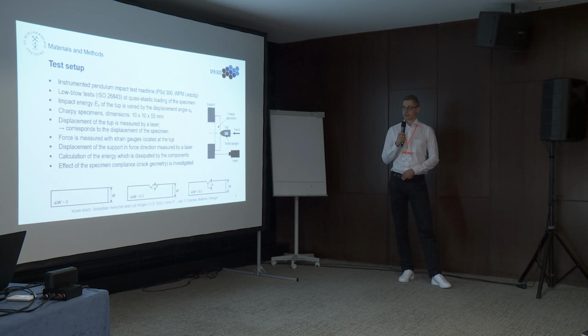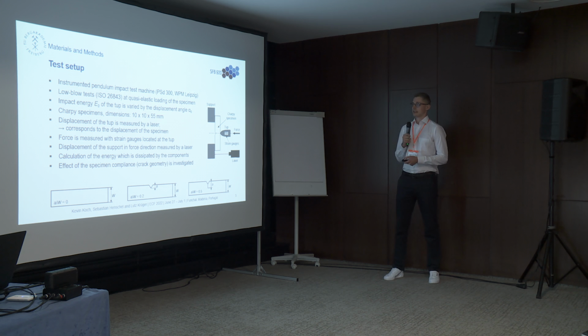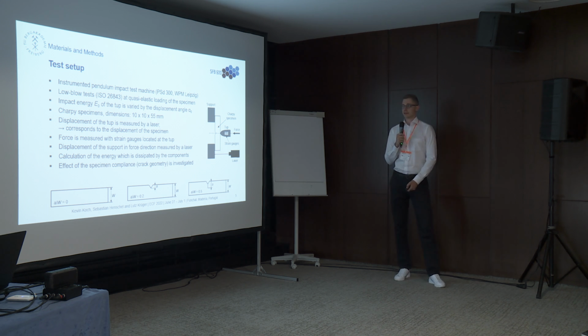Here you can see the top view of our impact test setup. The force is measured with strain gauges, which are located at the tup. And we also wanted to measure the displacement of the support in our tests to then calculate the energy which is dissipated by displacement of the support.